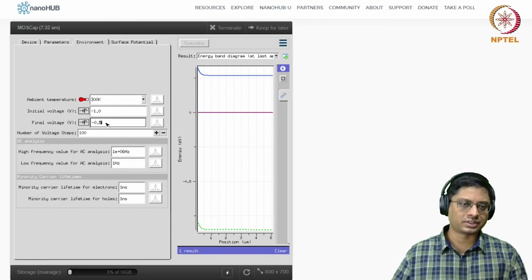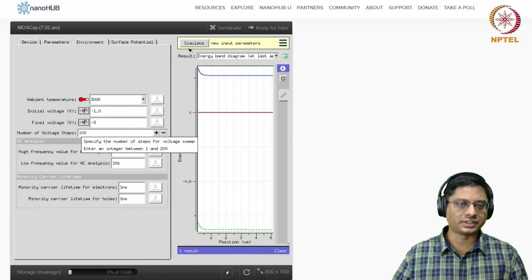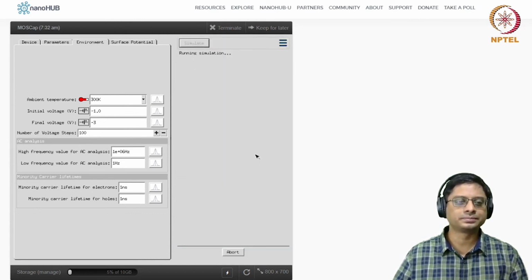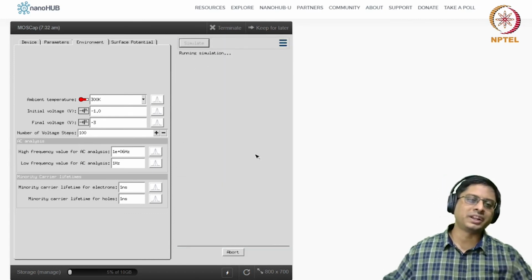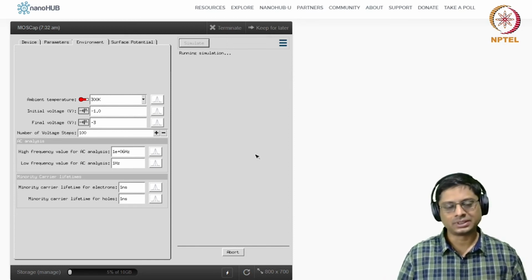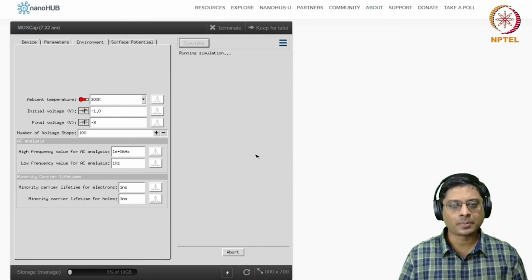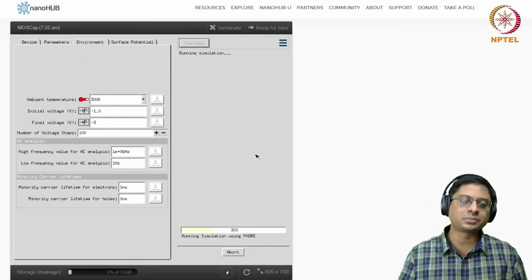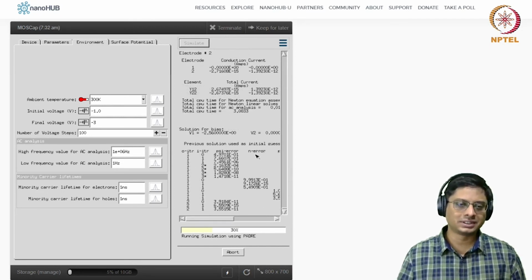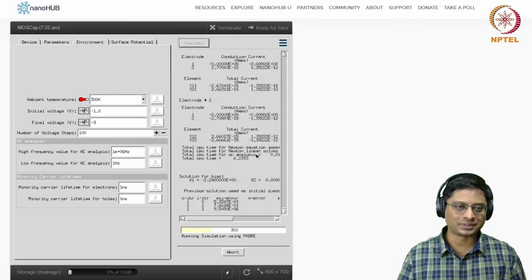That's fine. Instead of this, I'll go to -3 here, just, let's check it out. Let's see if it inverts at that time. So PMOS has to go to negative voltages to invert, whereas NMOS will go to positive voltages. There's a small correction term that will come about. I'll leave you to analyze what happens.